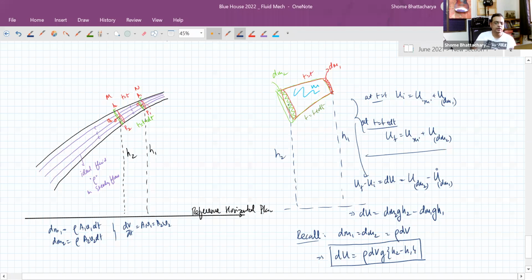So just like the continuity equation gave us a relation between area of cross section and velocity of flow at any 2 points, Bernoulli's equation will give us a relation between pressure, speed v and height h. Or in fact, it will be in the form of pressure, square of speed v squared and height h, compared for any 2 points within the fluid in motion, in streamline motion.